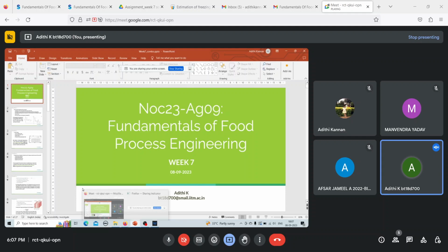And then we'll calculate delta T1. Delta T1 is (Ti plus Tfm) by 2 minus Ta. Ti was the initial temperature of the food, which is 10 degrees Celsius, Tfm you substitute from what you have calculated so far, divided by 2, minus Ta, which is minus 40. I hope this is clear till now. Delta T1 comes out to be 41.43 degrees Celsius. Is there any doubt in calculating delta H1 and delta H2?